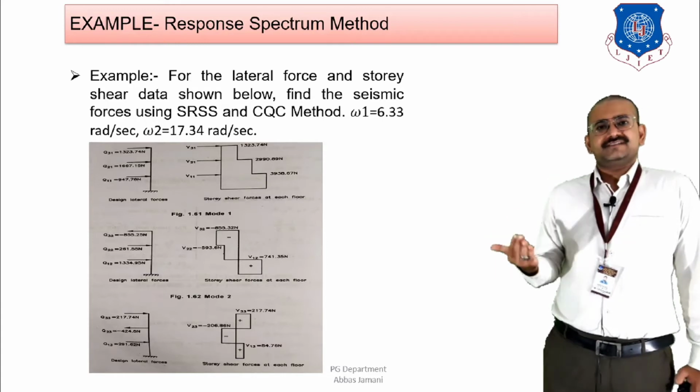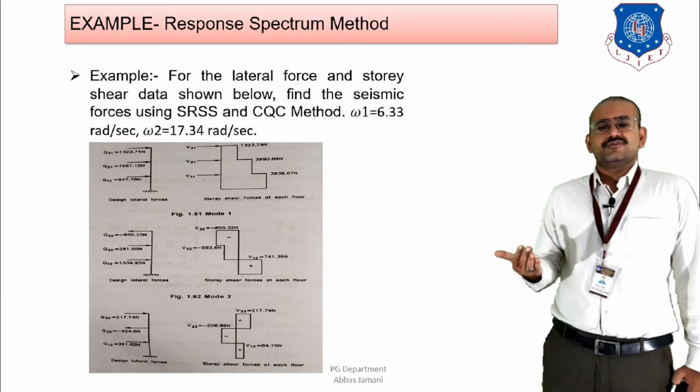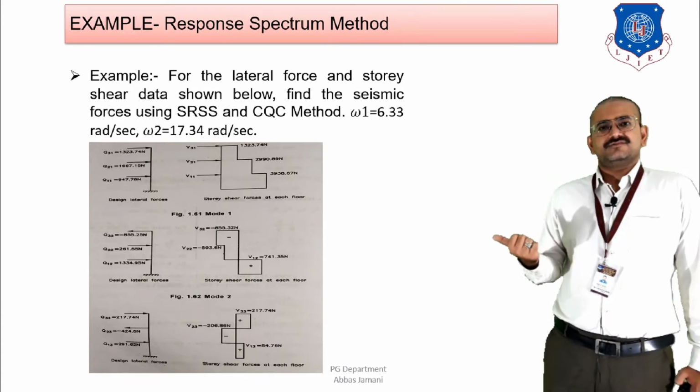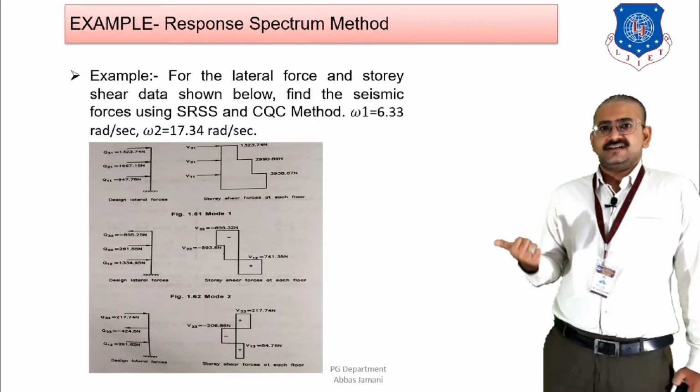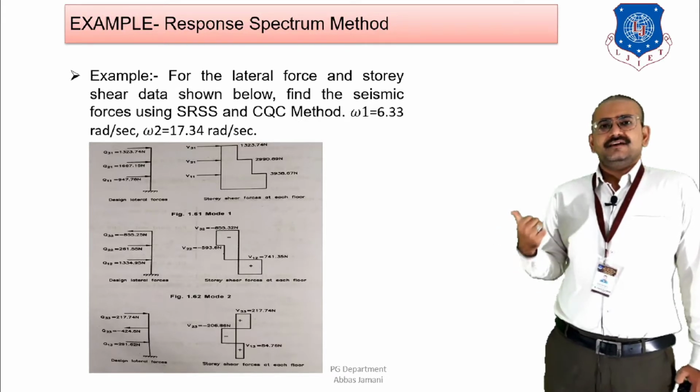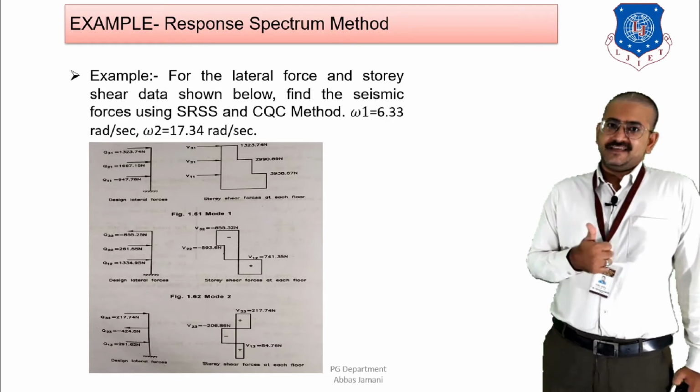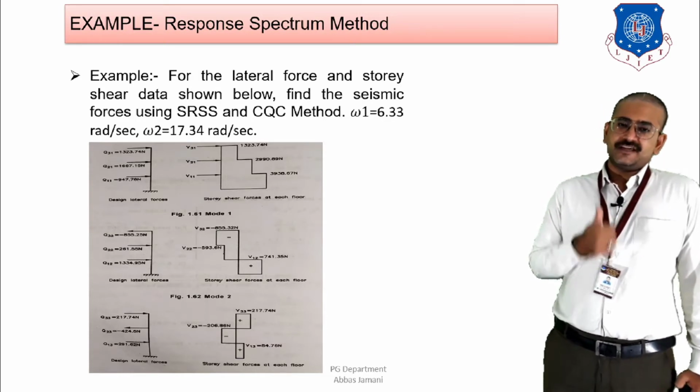From there on, the step forward is the calculation of combined modes, and in that case the CQC method or the SRSS method, whichever is mentioned, can be used to calculate the values of storey shear and the lateral forces for the combined modes, right?